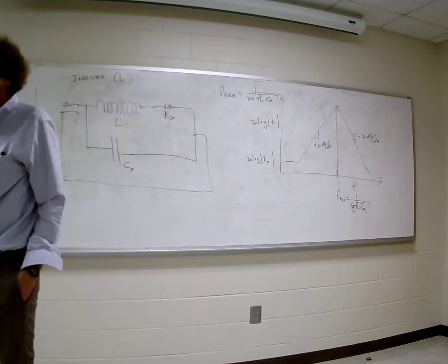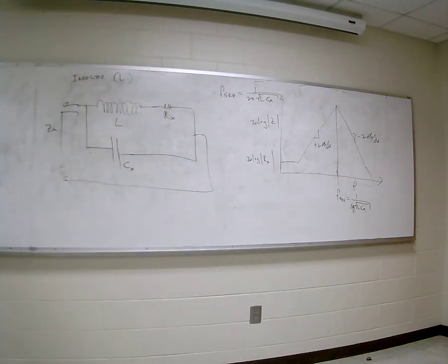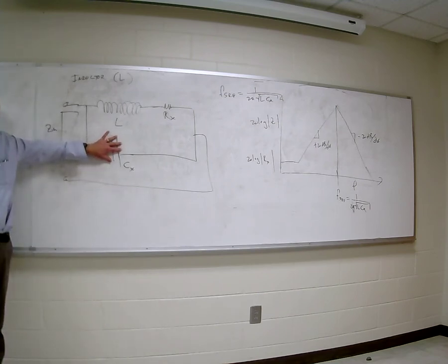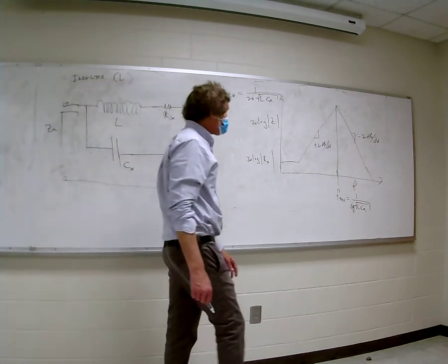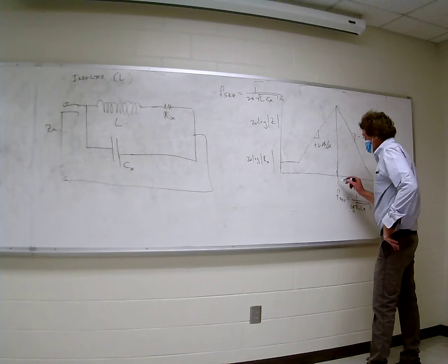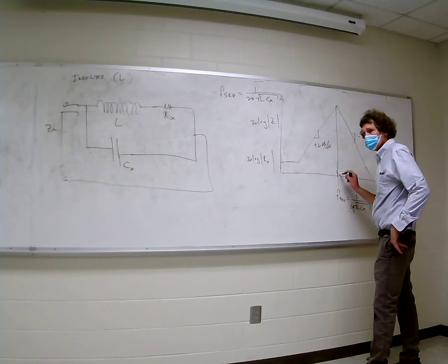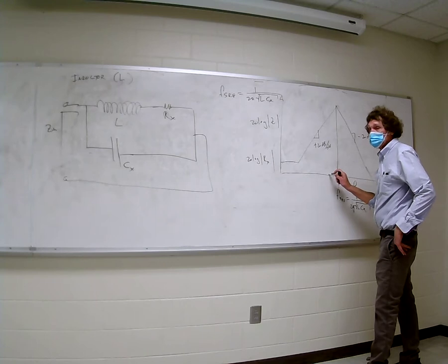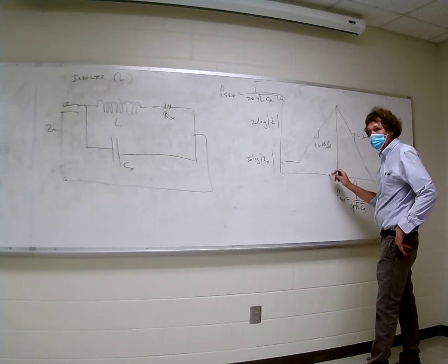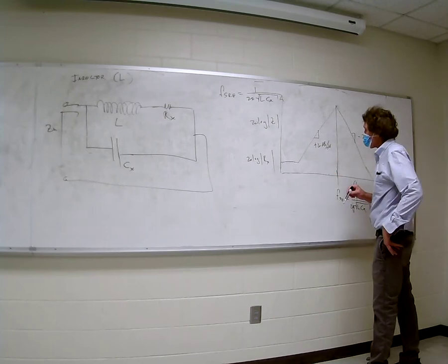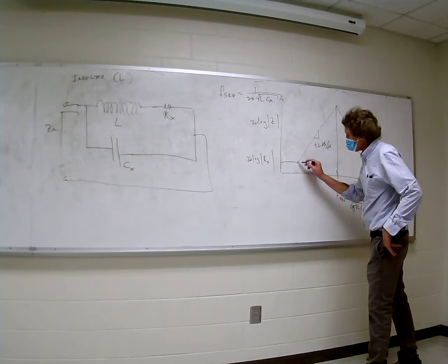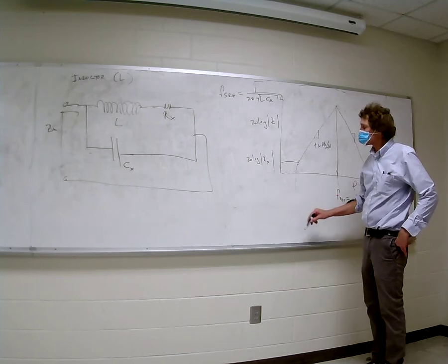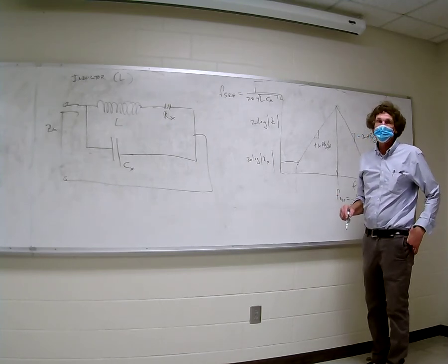Now here's why. For this one, at very high frequencies, this capacitor will be like a short circuit. There will be nothing to stop it. And the thing will just start looking like more and more of a short circuit. So if that's self-resonance here, and say it was at a megahertz, or maybe 10 megahertz, if you operated this thing at 5 megahertz, you'd be on the hairy edge. You'd probably have a problem too. If you come down an order of magnitude or so, you're usually okay. This is the one thing Dr. Wentworth's book does not mention. Where does this thing kick in at? And you don't worry about that.